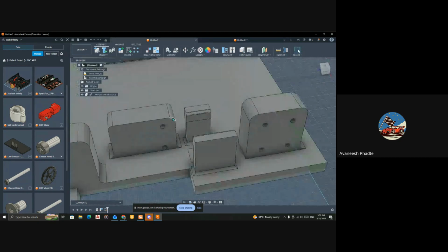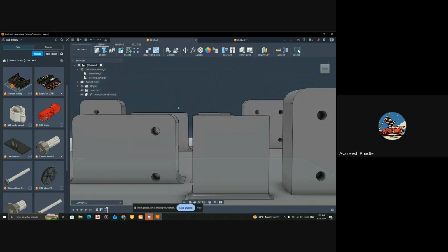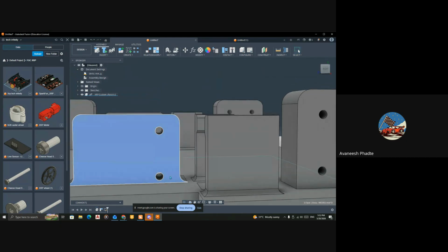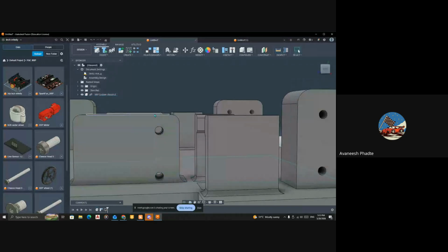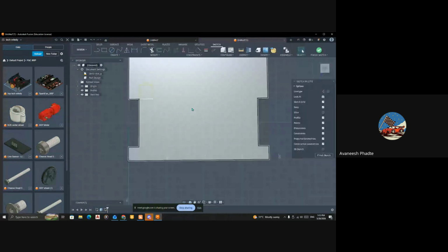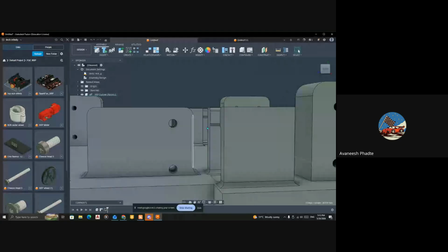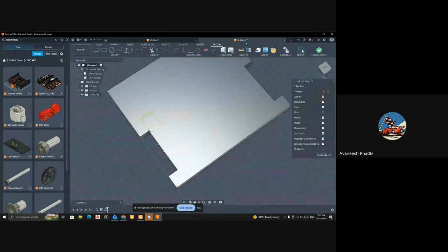Since there's a fillet over here, we cannot measure the exact height, but what we can do is click the bottom line and the top line instead of points, so that we can get the total length. Measure. So the total height is 26. We also need the length of this, so we're gonna like this, 39. So it's a box of 26 by 39.